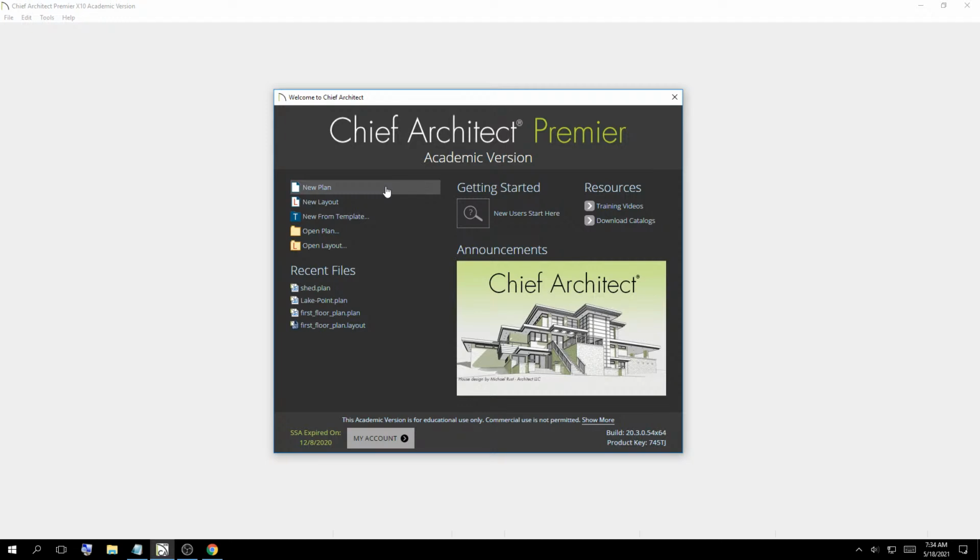So the floor plan itself, the nuts and bolts, the windows, the doors, the walls, the topography, and so forth are all obviously designed here in the plan, and then when you are ready to present to either an audience or send it off to somebody, technically communicate anything specific that you intend, you're going to be selecting a layout and then selecting what appropriate views, what size piece of paper this needs to be printed on, whether it's on a plotter and something large or something that's smaller on an 8.5 by 11 printer.